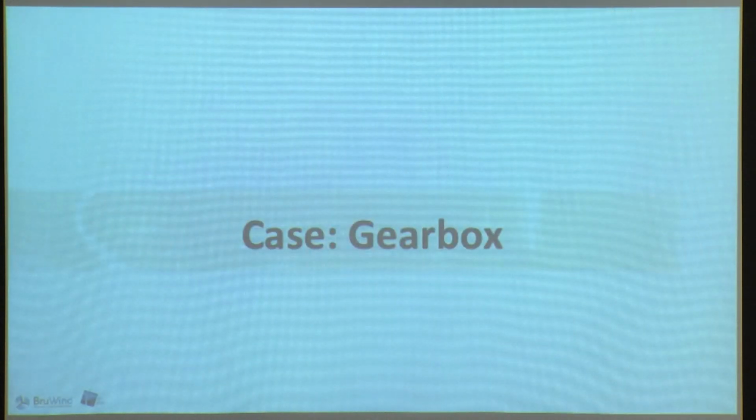But one of the components that has big lead time is the gearbox. We still see it today. If it goes wrong, you need to order it. You need to have this jackup vessel to take it out. So it costs you quite a lot of money. So it's a nice example to illustrate what monitoring can do and how you can use knowledge about the future to be smart about this.